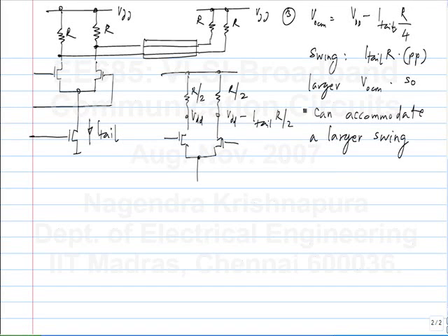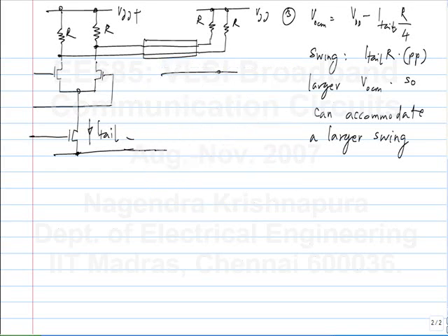What is the problem with this? This seems to be the best for transmitter design. What's a potential problem with this, or what's the flaw in the logic that I described so far? Actually, yeah, that is the big problem. This VDD is with respect to this ground here, and you need to have basically the same ground and the same VDD. And one of the first things we discussed in this class was that you can't really have them to be exactly the same.